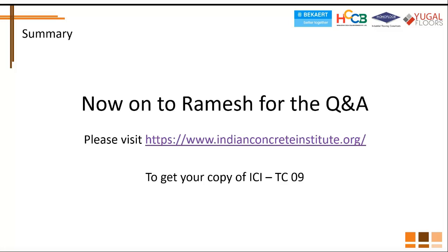Second thing, we need to understand that typically in Indian conditions, there's a 4 to 5 hour lag between the time you place the concrete and you start finishing. And with the kind of weather conditions we have, a lot of water actually evaporates in those 4 to 5 hours, which none of us ever think about. We'll be happy to share the nomograph that establishes a relationship between the wind speed, air temperature, concrete temperature, and humidity. You can do your own calculations. You would realize that a 0.5 water cement ratio actually ends up being a 0.4 by the time you start finishing, and we still need water for the hardener.